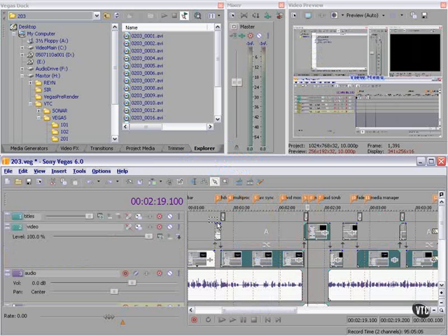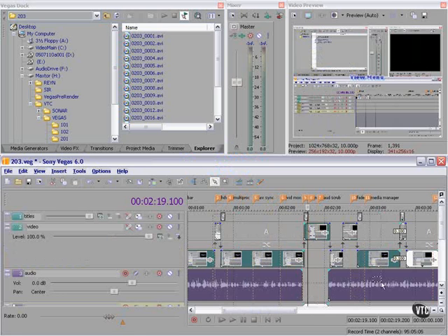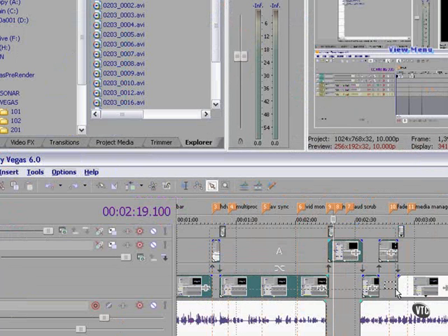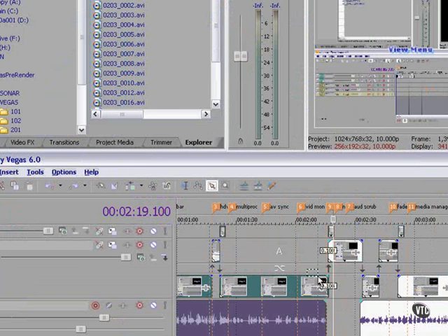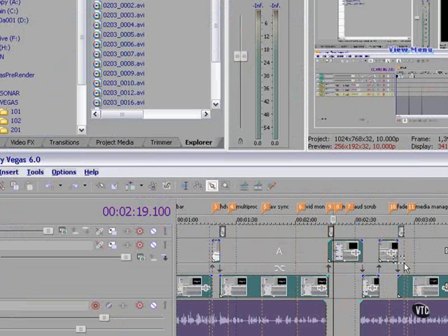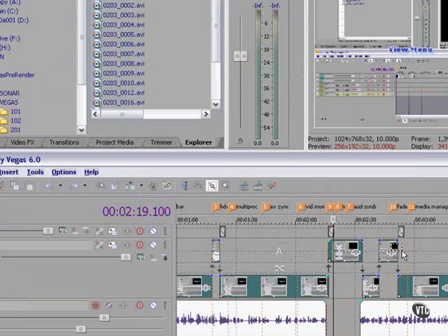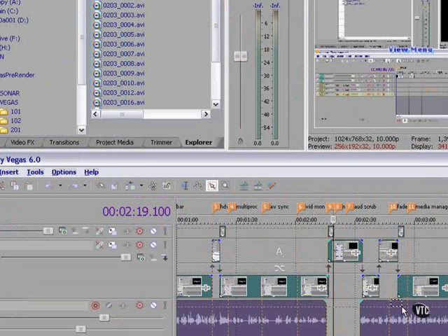Use the Selection Edit tool to select events across tracks. Notice that it creates a rectangle, a little box there on the right. Can you see it? If, while holding down the left mouse button, we click the right mouse button, we can constrain this to the vertical direction. If we click again on the right mouse button while holding the left mouse button down, it switches to horizontal selection. And if we click once again, it goes back to normal.